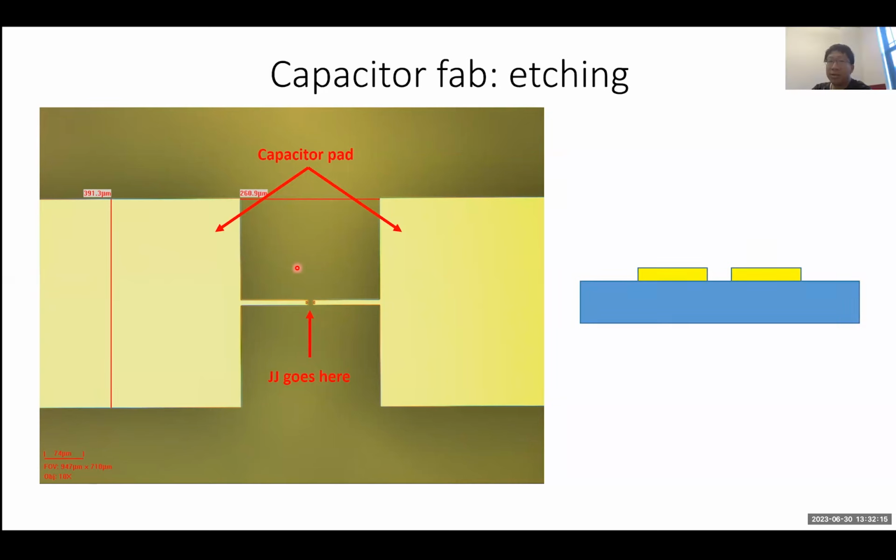So there's also a question on the impact of strip on the metal, like niobium or tantalum. It's actually not exactly clear to me what the question was, but I imagine the process of stripping away your resist, is it going to impact your metal surface quality? Yes, it could. If you don't do a good enough job, it can definitely leave some residue. The nice thing about working with materials like niobium and tantalum is that they're highly chemically resistant.